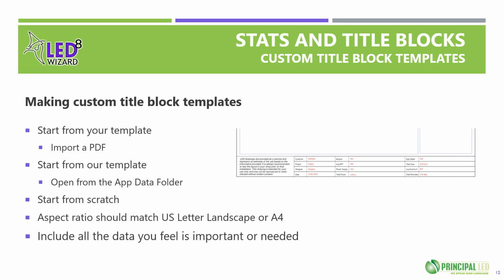As I mentioned, if you create a layout and you merge it with a title block template, you can export that. You can take that same layout, change the title block, and merge it again and export a different PDF. And now you've taken the same file, the same layout, which hasn't changed, and you've exported two different PDFs out of the same file. And that's a pretty legit way to do it.